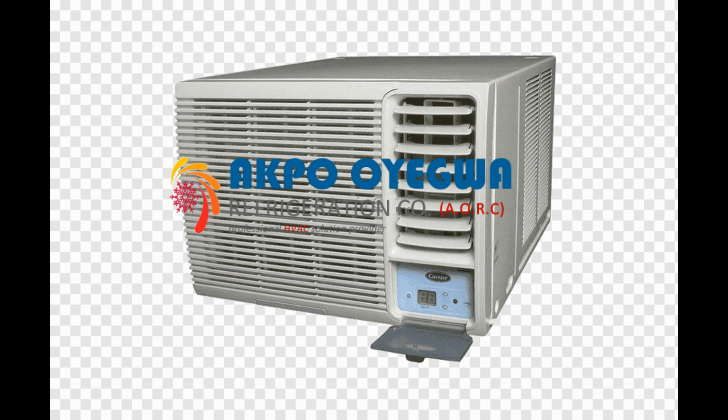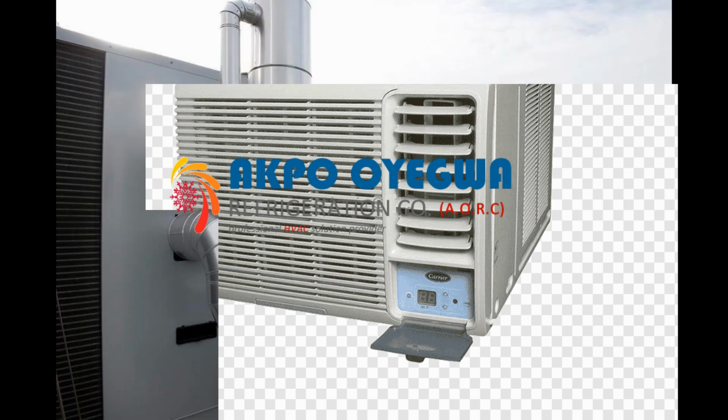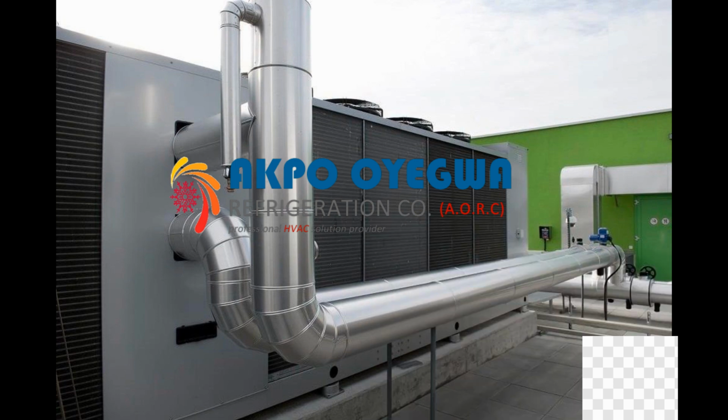5. R744, carbon dioxide. This is a natural refrigerant with zero ozone depletion potential and a low global warming potential. It is used in some commercial and industrial applications, but it has a higher pressure than traditional refrigerants and requires special equipment.